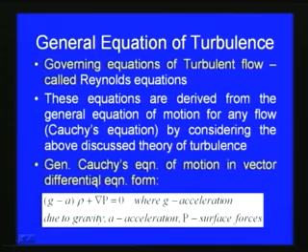So, we can see the general Cauchy's equation in standard literature; anyway, we will be discussing it further when we discuss the Navier-Stokes equation. The general Cauchy's equation is with respect to the acceleration components: due to gravity and other accelerations multiplied by rho, plus the surface force variation del P, is equal to 0.